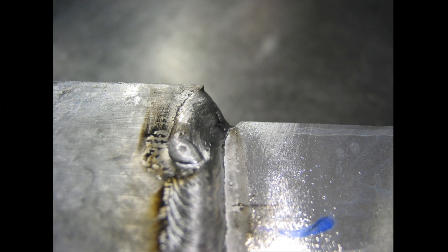Because see, you put a sign on that, say crack here. That's all you're telling that right there. If you wanted to find a way to make that weld fail prematurely, you could take just a hacksaw blade and cut down into it in the same fashion. And it would take this heat affected zone, the area right beside the weld here, and it would just split right down there very, very quickly. So that's part of the problem. Not only is it notched, but it's notched leading right to a heat affected zone condition, which is just a little bit softer.